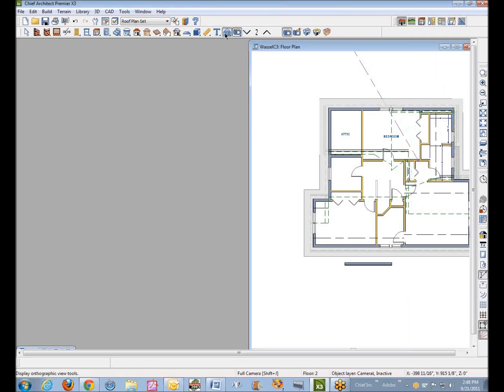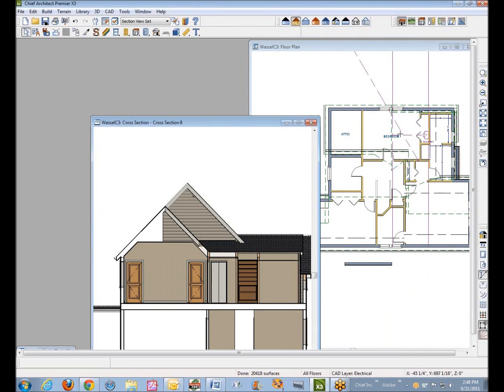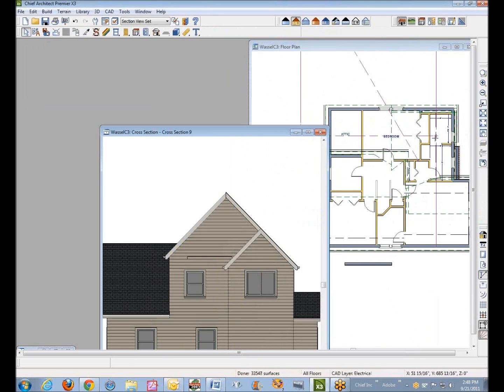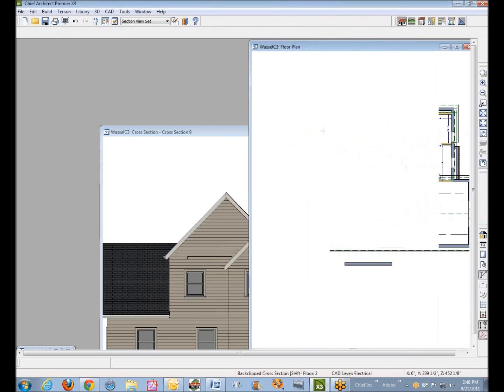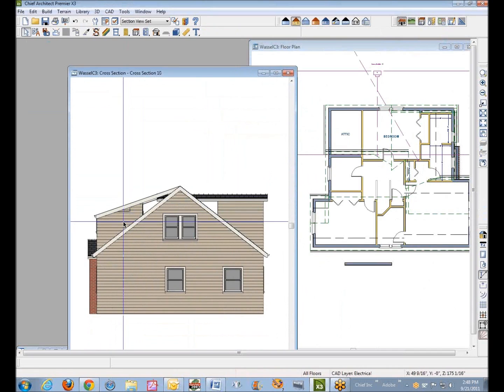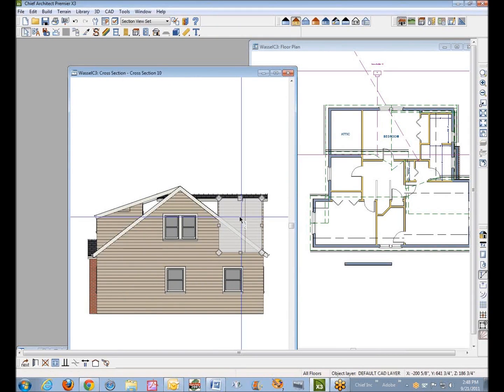I'm going to use an elevation camera with a back clip on it. I think it's right along in here somewhere. I want to get a perpendicular view to that. Is that it? No, I don't see it. Give me a moment. I'll find the silly thing. Nope, that's not it. Let me try this way. There we go. You can click on that and then hit the tab key, and then that's the wall polyline. And you just don't have enough wall to fill in there.